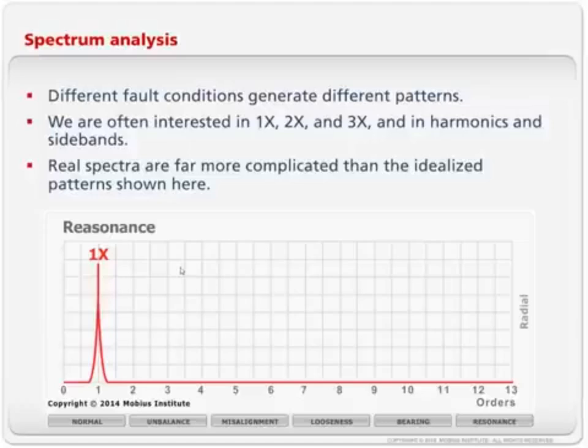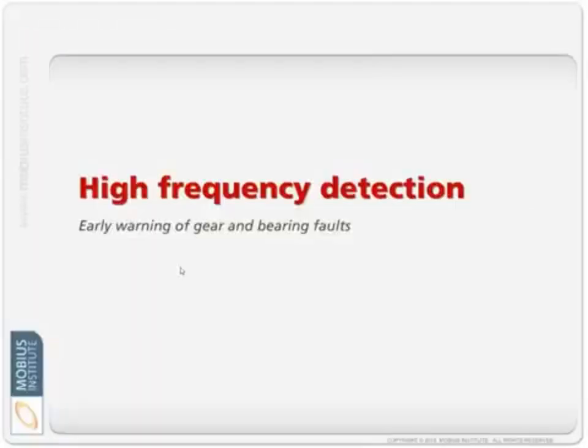And we can take that information, we can watch how the vibration's changing, and then we can make the recommendation: does the bearing need to be replaced? Is it a problem with damaged rotor bars? Is the problem with the coupling? Is there a problem with the foundations? I mean, all kinds of problems can be detected this way.